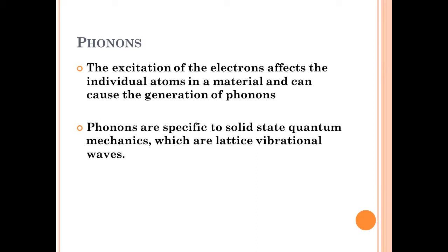Excited electrons can lose their energy by transmitting it to an oscillation about their bonds. This occurs when the atomic vibration energy is transmitted through bonds, causing local atoms to start oscillating as well. This causes a vibration cascade throughout the material. The result is the generation of a phonon, which is a vibrational wave of atoms in a lattice, associated with atomic shifts. Phonons can be considered quasi-particles.